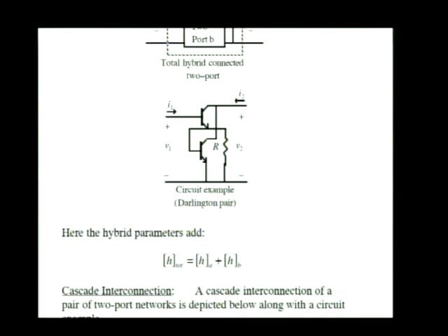So what I would do as an intermediate step is, once I found the z parameters of the series interconnected pair, I do the conversion listed in the textbook using the table there, from z parameters to y parameters, to get the y parameters of that first pair, and then combine that first pair with the next two-port that's in a shunt interconnection using y parameters, which are most convenient for shunt interconnections, to find the y parameters of the overall